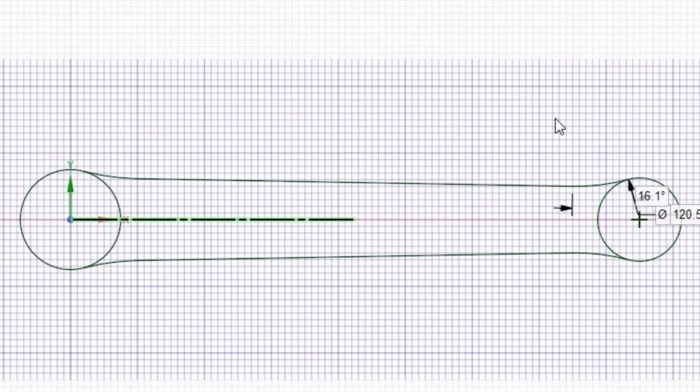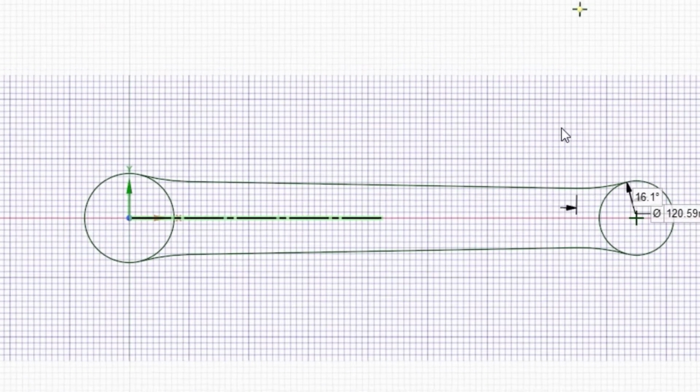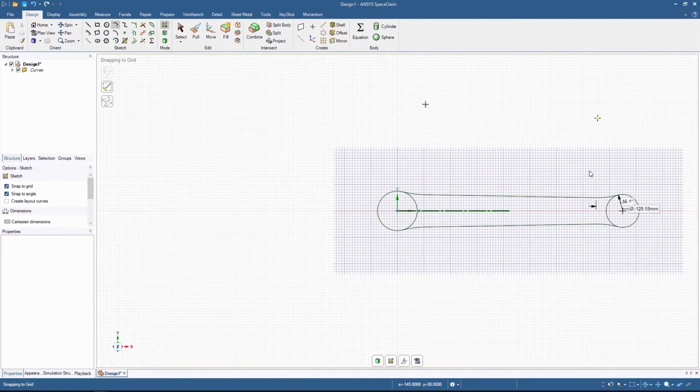Notice that the tangent curve also gets created on the lower side of the horizontal axis. We now have our outer sketch ready, but we need to remove the intersections of the two circles in order to create a single closed profile. Select the Trim Away tool and click the inner circle sections to delete them. The sketch is now ready to be converted to a solid model.